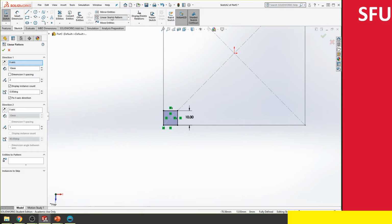Actually, maybe the circular pattern is easier. So in this case, I would actually move it by 100 minus 10. So I would basically move it by 90 degrees. So I only need one copy here along the X, one copy here. So I'll make this 90. Oh, okay. I need two copies actually. So I'll make this 90.